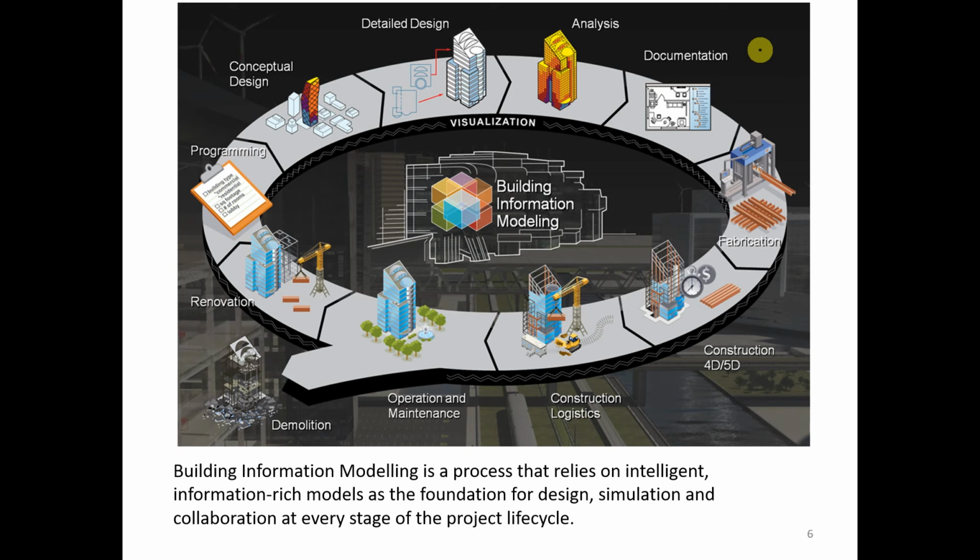And Navisworks is where really the essence of BIM, Building Information Modelling, comes together, because in Navisworks you actually pull in the architectural, the mechanical and the structural, overlay all three, and having done that, the software can then highlight any clashes.